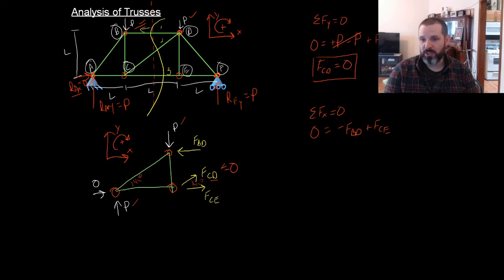so I'm going to need to move on to my moment equation. Now, you can take the moment at any point in a structure, but just like when we did the reaction force and we summed it around A, we had two reaction forces acting at A. We didn't want to have to worry about those forces, so we summed it at the point where they intersected so we didn't have to consider them. That same thing works when we're doing this section cut.